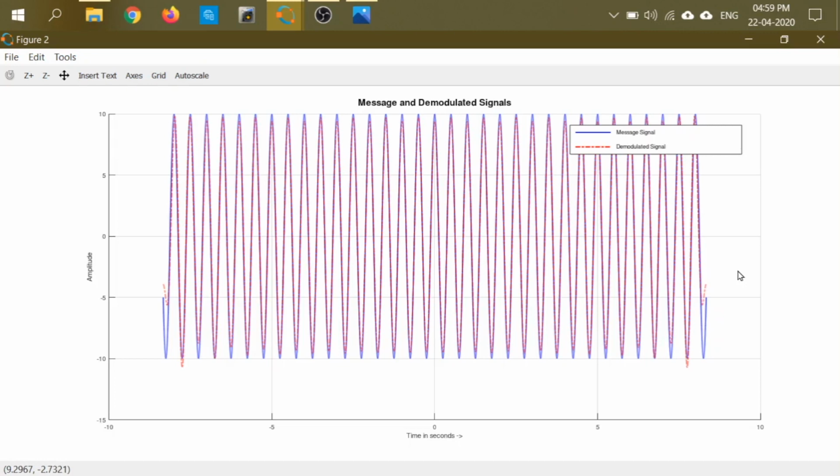And in the output, there might be some DC term also. Although, in my coding, I have removed the DC term. It's not necessary that both of the signals will have this DC value equal to 0. The DC value can easily be removed by using a capacitor in your hardware circuit. So these two changes in the signal could be there if you see the output for yourself by running this code for different signals: amplitude variation and a DC component. These two signals can differ by that. But for my coding, I have removed that effect, right?